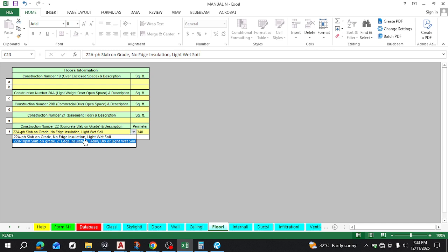We are going to assume worst case scenario and then select that it doesn't have insulation, unless our file tells us that it does. Because the whole point of this, we are trying to get the amount of cooling or heating needed for this space. So if we assume that there's insulation and then there ends up being no insulation on site, means our entire calculation is going to be null and void, because whatever sizing we do is not going to work for that space. So we're going to assume that it is not insulated, which is the worst case. Now in case it is insulated then it still falls under the range that we are going to get from here.